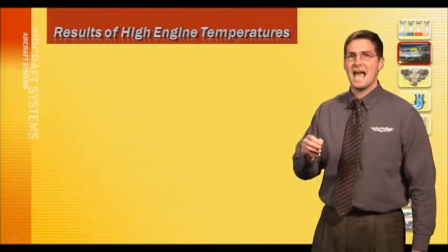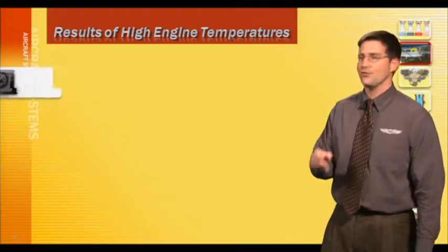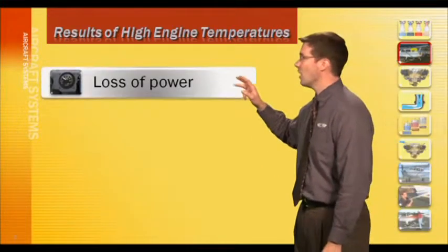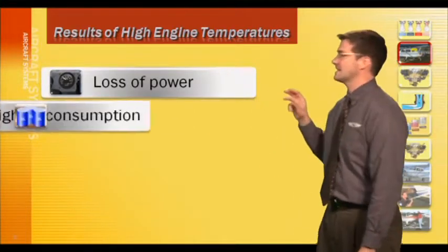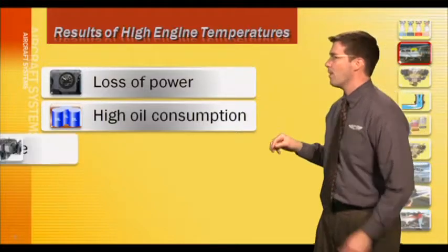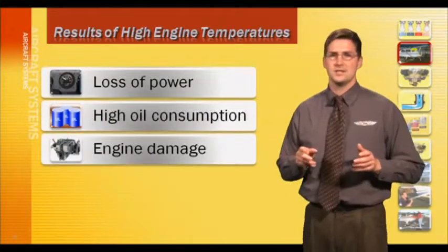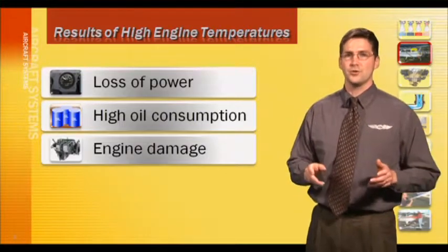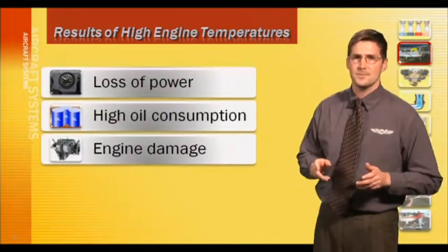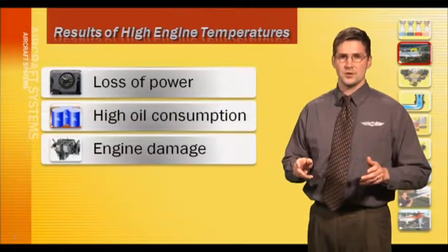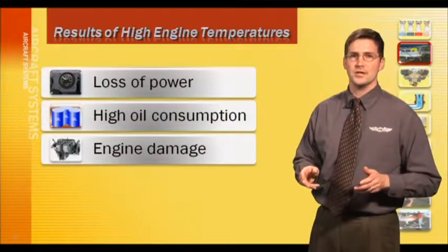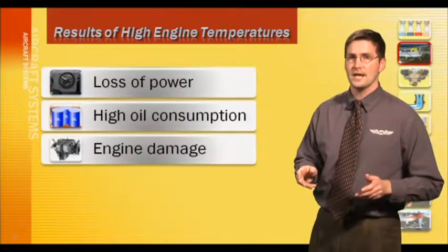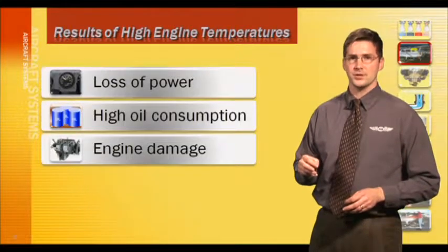Now, excessively high engine temperatures may cause the following situations. First of all, a loss of power, excessive oil consumption, and possible permanent internal engine damage. If the engine overheats during climb out, reduce your rate of climb and increase the airspeed. In other words, lower the nose to increase airflow to cool the engine. Now, if it's still overheating, try to enrich the fuel-air mixture.